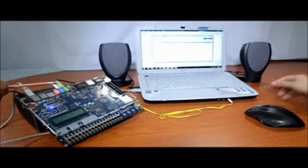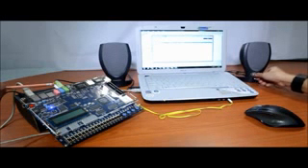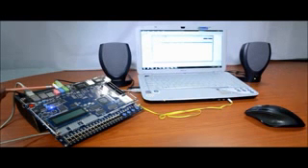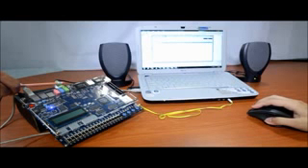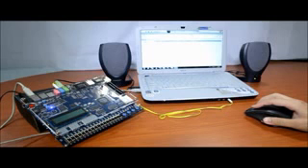Connect an audio source to the line-in jack on the DE2 board and connect a pair of speakers to the line-out jack on the DE2 board. Play the audio. You should hear the audio streaming from the speakers or headphone.